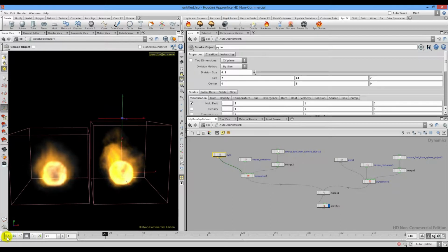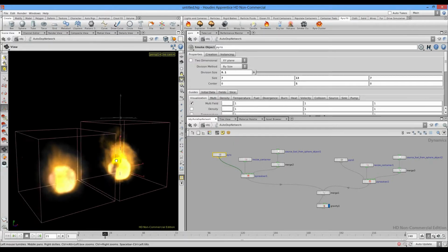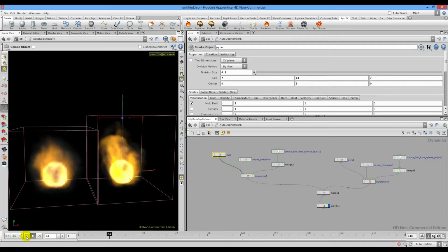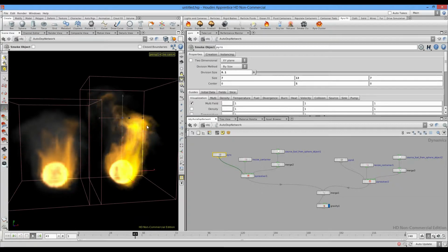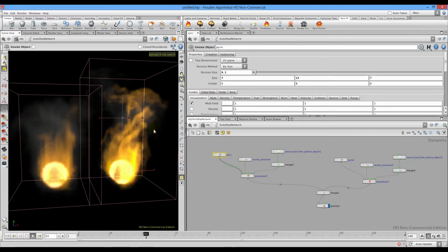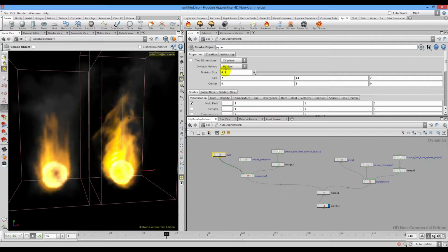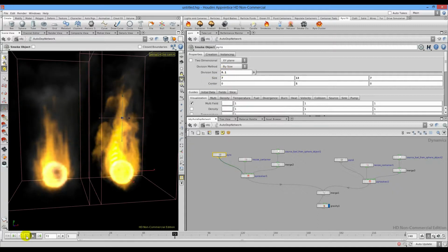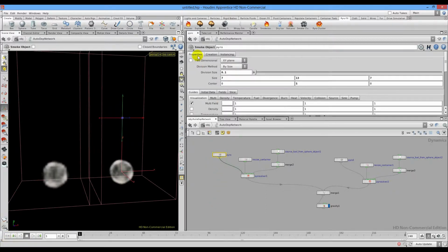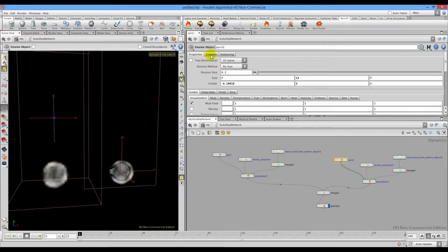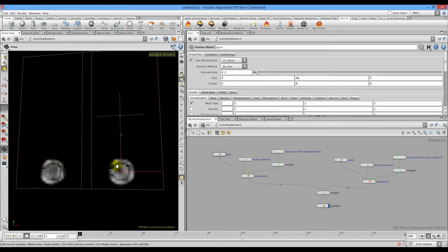If I play this, well, even without playing, you can see the quality difference in the flame. Yeah, way more detail, and the flame becomes more interesting and very detailed. But again, 0.1 is pretty low resolution because it doesn't keep all the details which can be here. So I will set both of them to two-dimensional, and we'll set 0.2 to both of them like this.